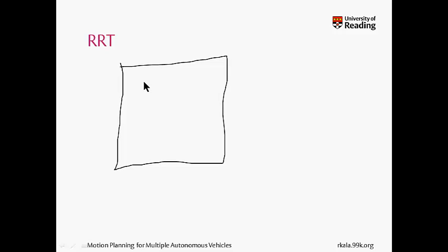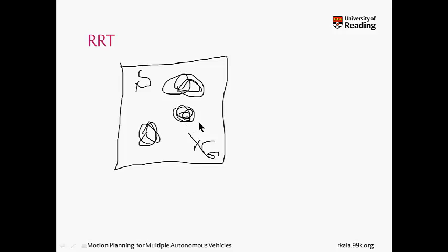First, from the point of view of mobile robotics, if this is the source and this is the goal, I need to find the trajectory that connects the source to the goal, given there are some obstacles around like this. Now from primitives I know that graph search is a very good technique to find such trajectories. In fact, graph search algorithms have long been the algorithms of choice for all such problems. If I can have a graph magically appearing here, then I can solve the problem as a standard shortest path graph search problem.